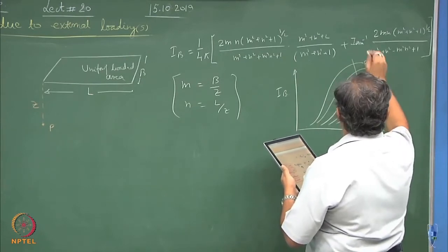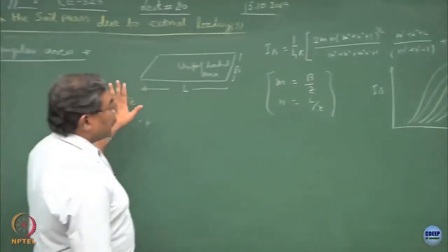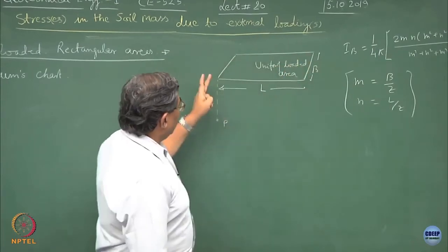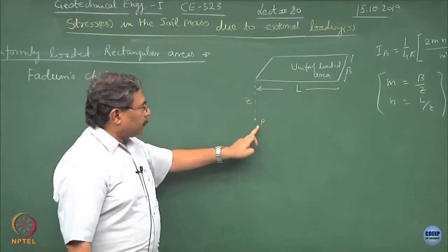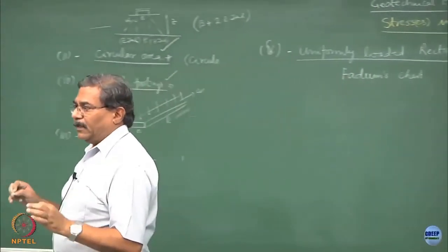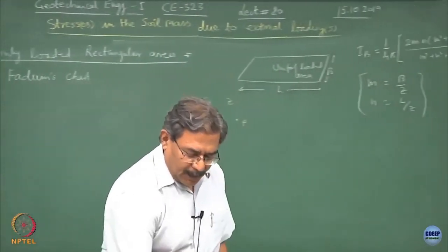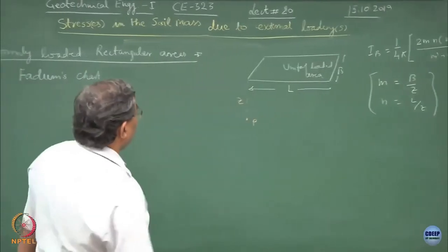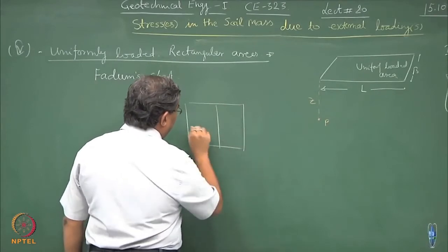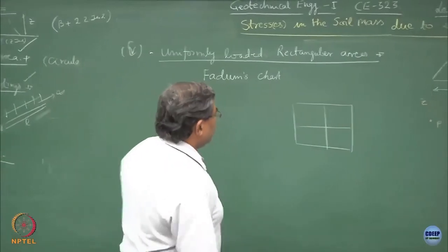Alright. This is a peculiar solution, one of the solutions I would say. If you have a uniformly loaded area of B and L, and you have to find out the state of stress exactly at the edge or the corner point of the loaded area, alright. Manipulations can be done in several ways. I hope you will realize and enjoy that if I have a uniformly loaded plate, let me not segmentize it first.